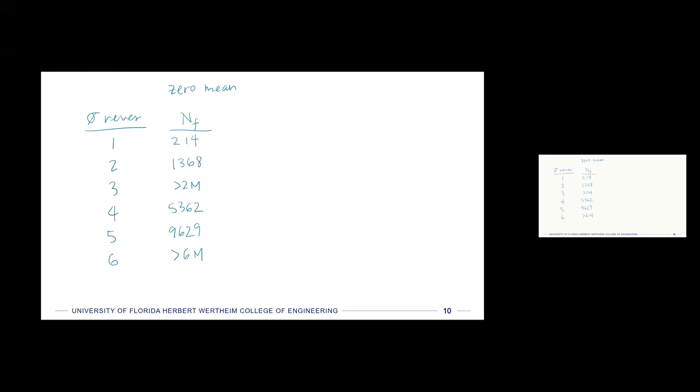If we calculate R for each of these to represent the non-zero mean stress, the first one is minus 0.43. It's just the minimum divided by maximum. So if the minimum is negative, then R is going to be negative. If they're both positive, then R will be positive. 0.16, 0.8. We had one that went to 0, so R is 0, minus 0.67, and minus 1. So these values can only really range from minus 1 to 1.